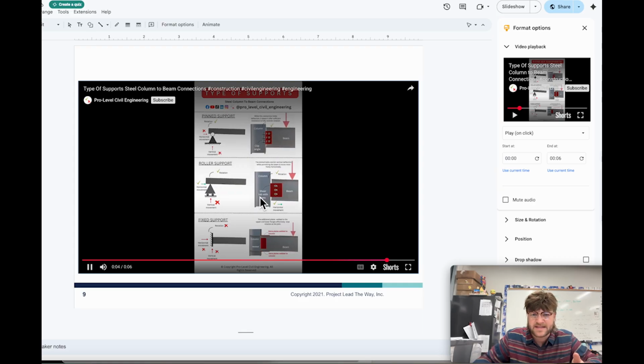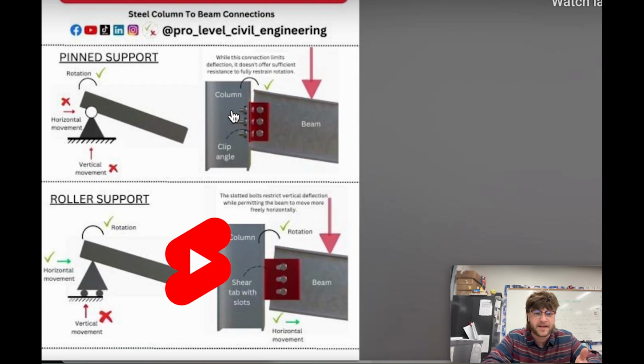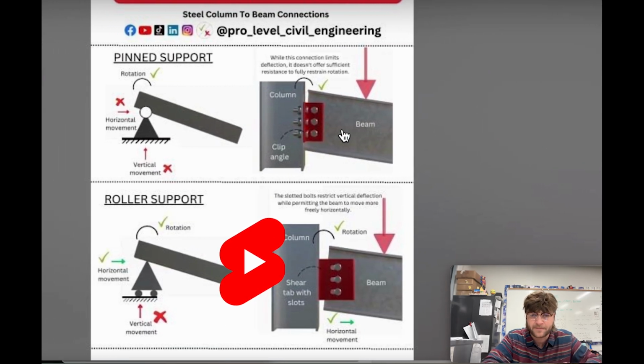So you can see those. And if you end up bringing up the notes in class, you can zoom in on this a little bit better. But yeah, here we go. So we can zoom in on this right here. If we have a pinned support, remember that's where rotation is allowed. We're actually not going to have any reaction moment. And so how that correlates into real life is something like this.